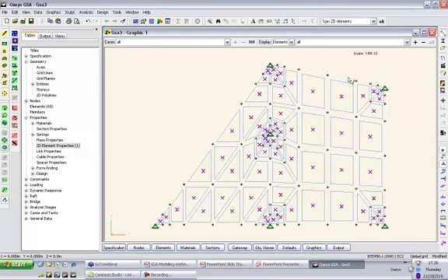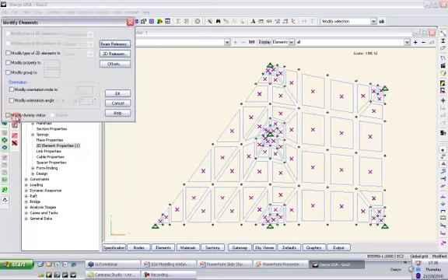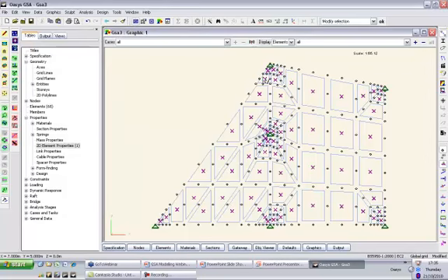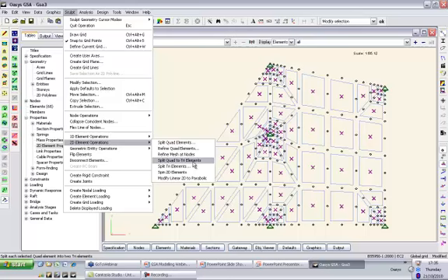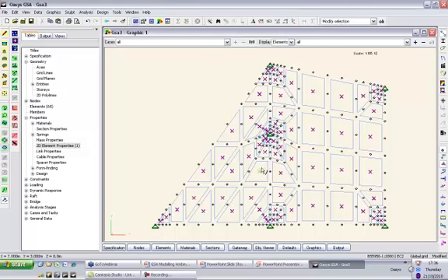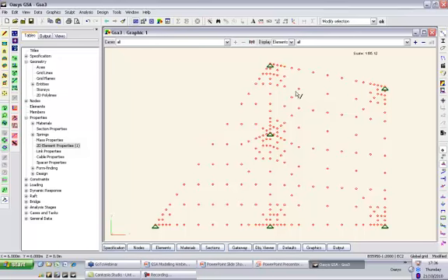If I select all these, we can modify them over to parabolic, which adds in mid-side nodes and additional Gauss points and so on. And there's also a sculpt command to directly do that down there. Now, as I mentioned, this is not a particularly neat mesh. What I'm going to do is delete out all these 2D elements.